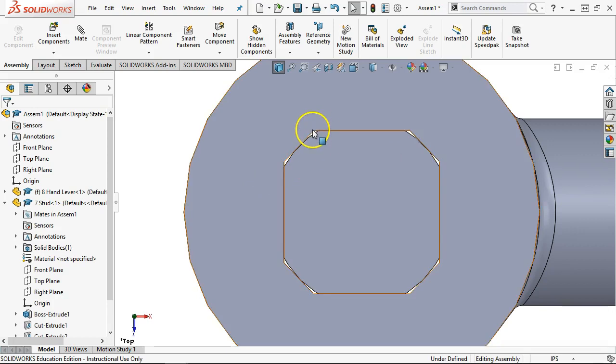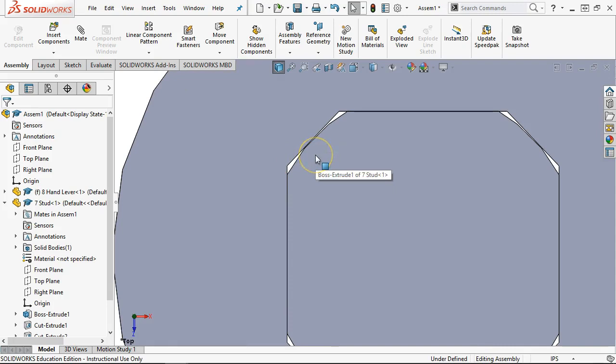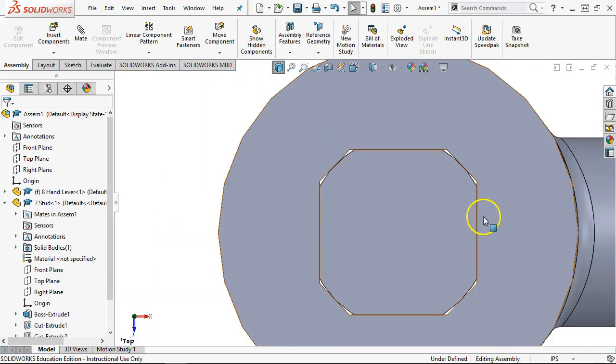I still don't think that I can get that corner to go to a radius with any kind of size. I mean, the flats, we're going to have to drill a 7/16 hole, and then some way come in, round off the corners, and the half-inch that continues on through here.